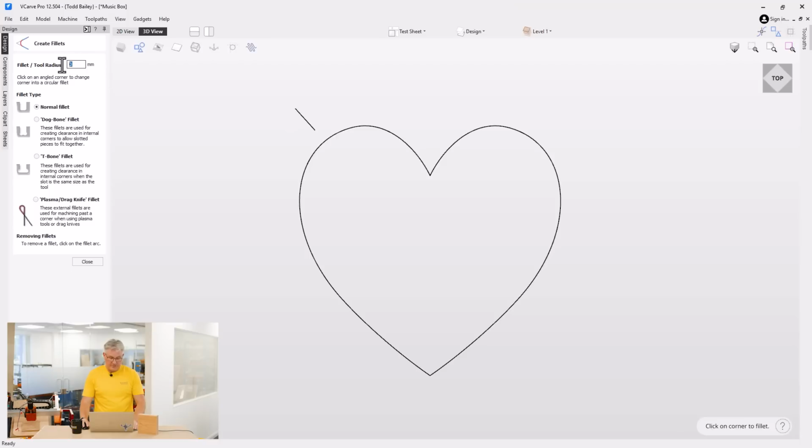and we're just going to fillet this a little bit in the middle. So let's fillet this about 0.635. I think that'll be all right. No, sorry. Let's make it, so 6.35 is the diameter of my tool. Let's divide that by 2 and make that the radius of my tool. And let's just go ahead and click that. That looks good. And we're also going to click this one down here.